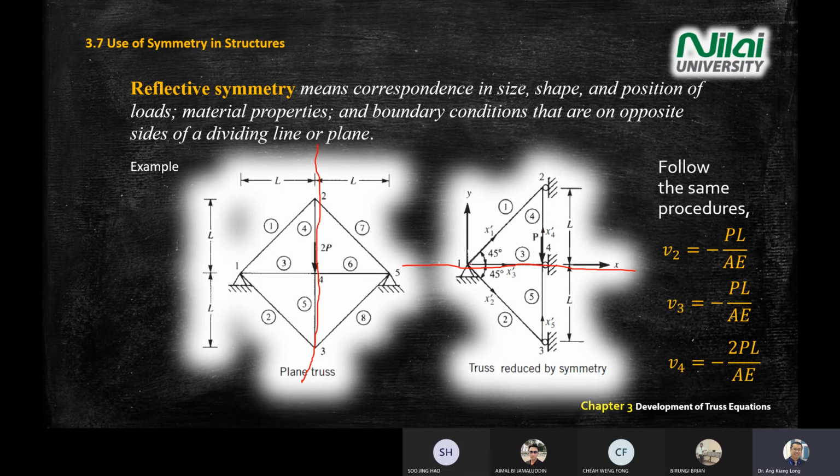You can cut half and then do the analysis on one side of the structure. This is what happens when you use software. We call it symmetry analysis, where you only need to draw half of the object, then you will see the projection of the same results as if you simulated the whole thing.